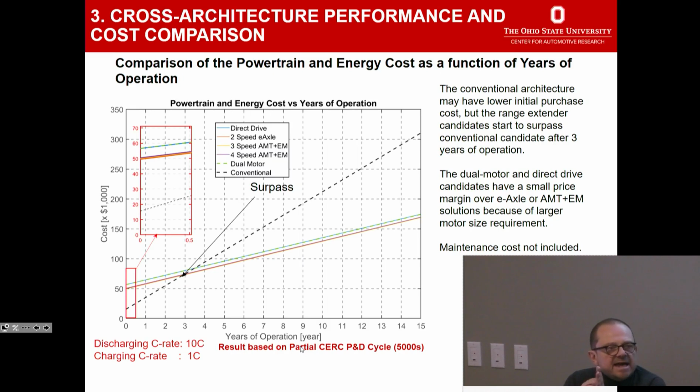I now can say, hey, I can really improve your ton miles per gallon freight efficiency, but it'll cost you $50,000. Now, that's not an insignificant change in cost. Sure, the vehicle overall is much more expensive than $50,000, but that's a significant increase in cost. We've more than tripled the powertrain cost. So how long will it take me to recover this cost? Because if I have better freight efficiency, I'm saving money because I'm using less fuel.